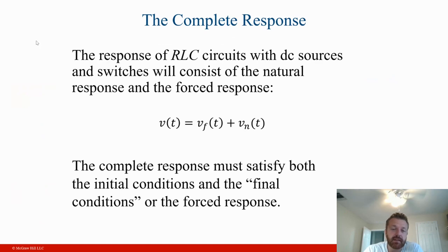Namely, we can always conceptualize the response or the solution to any differential equation as the sum of the forced response, which is going to be kind of dominant in the long term and due to the actual sources present within the circuit, plus the natural response. And the natural response is just the source-free response. It is associated with the energy stored in the circuit as a function of the initial conditions.